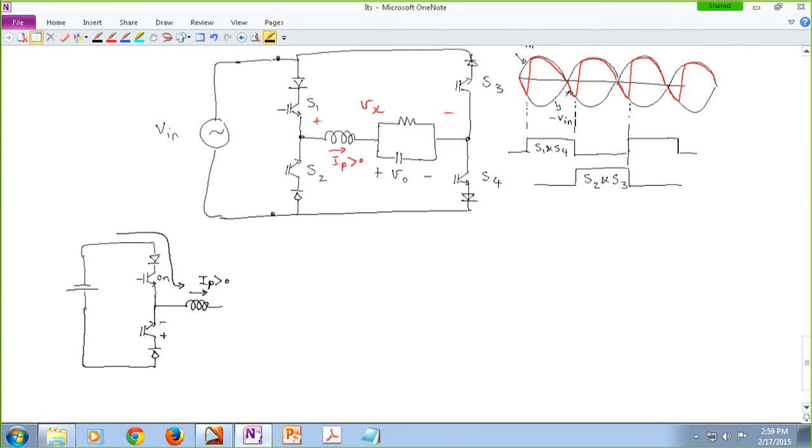So this bottom transistor is actually blocking the voltage. All of the diodes are trying to conduct. Even if you look at this voltage over here, it agrees with the polarity at which the diode would start conducting. But there is no possibility for this to be on because the transistor at the bottom is off.